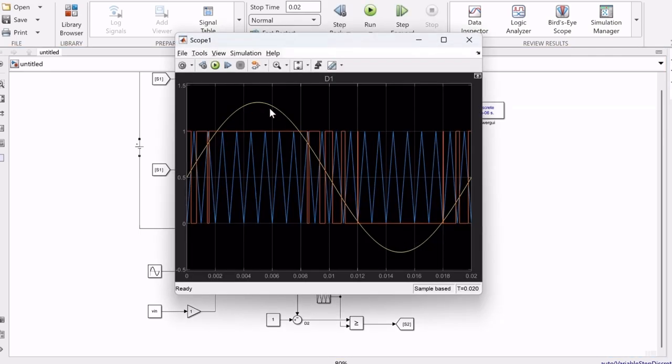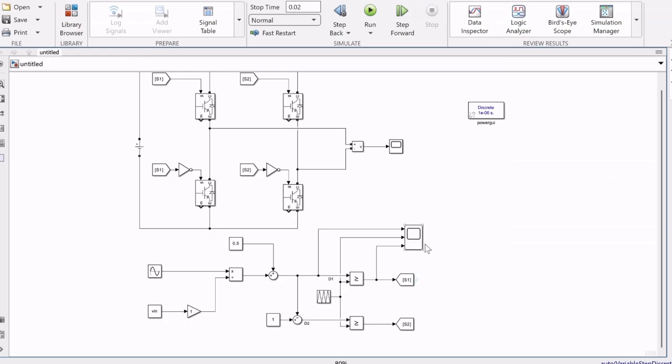Yeah, so we have overmodulation, which means that the duty cycle is larger than 1. So this would obviously not work. We need to find the error in how we calculate the duty cycle.